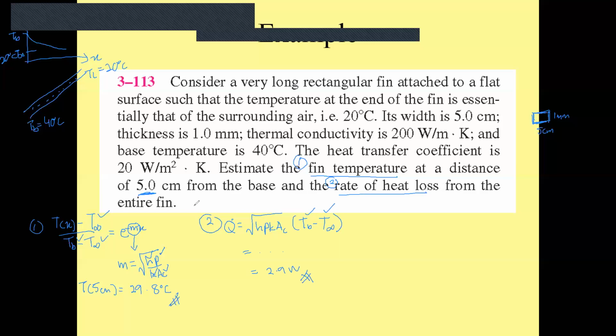Okay, it will be as simple as applying this equation if you know what case it is. So in your answer later on, I want you to discuss first how you choose this equation, right? So you're going to see, for example, because the fin tip is at the surrounding temperature, it can be assumed that it is a very long fin. Okay, it's a very long fin because we only have 4 cases.